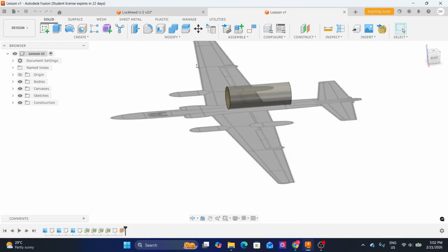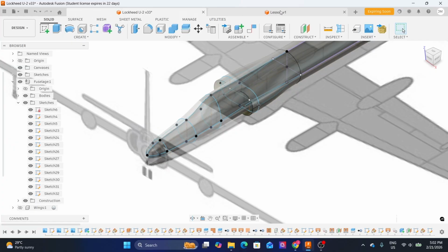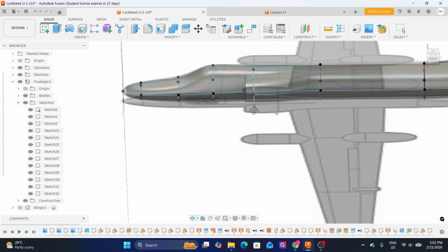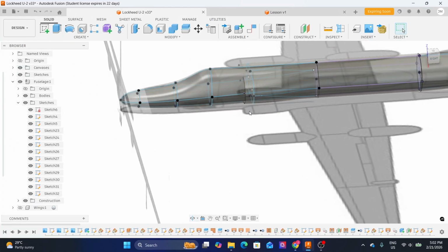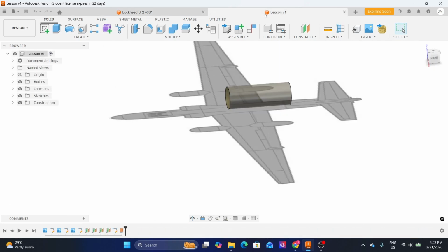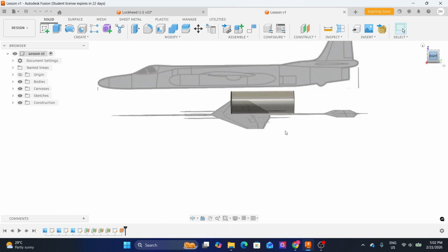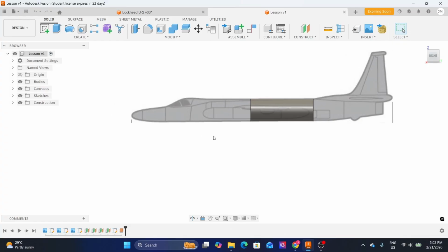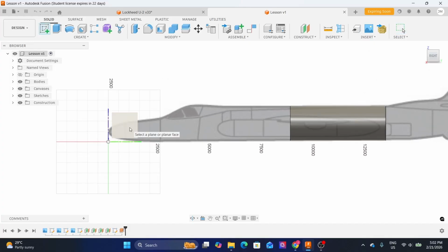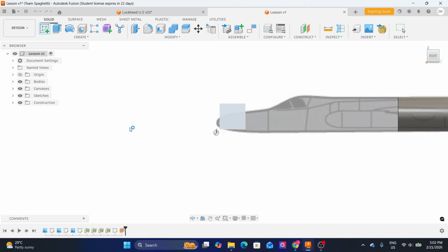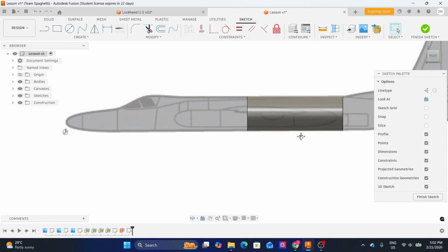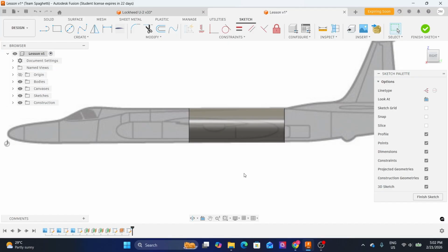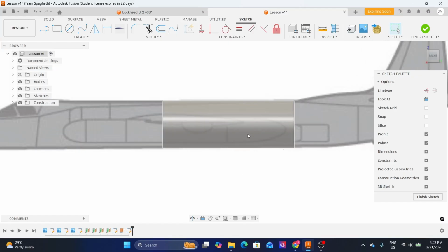And by the way, I'll be switching tabs maybe in this video, since I'll be referencing the model that I have already created. So let us go ahead and create again our sketch. So again here, I'll create sketch. So I'll select this, and then I'll select this face, the right side face. And then, before creating any sketch, what I would like to do is project the 3D body that we have already created.